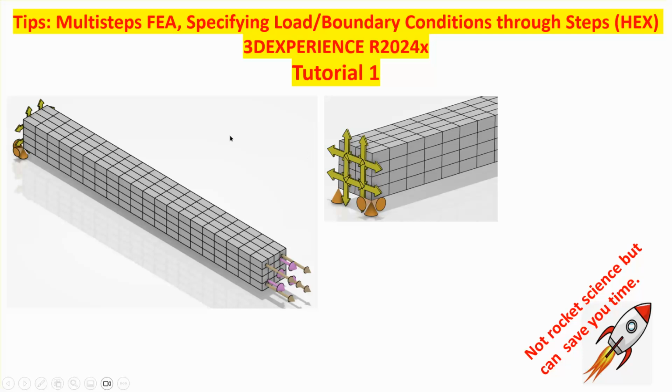On the left side, instead of clamping it, I use the so-called 1, 2, 3 rule. In other words, one point is completely fixed. This face is put on a slider, and this is prevented from moving upward, and therefore it cannot tip over.